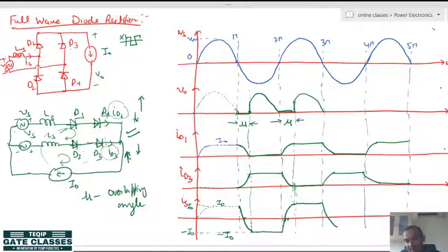This is the source current here. You can see here, due to the effect of source inductance, the current does not change instantaneously. All right, and this also affects the output voltage, that it results in another 0 output voltage, meaning it further reduces the average output voltage value. So, if you consider this first cycle, this will never happen again. So, we can draw the first cycle like this only.